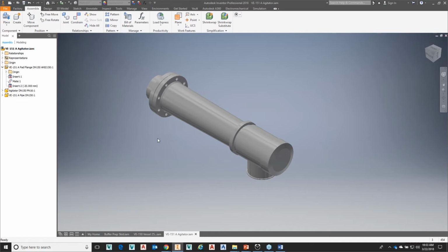So it starts early. We're going to go to this sub-assembly and we're going to create a different way to represent this, right? Now, under level of detail, this is different than just turning on and off the visibility of parts. This actually starts unloading them from memory. It makes the numbers at the bottom right go down, right? And as long as those are going down, we're unloading those from memory and hopefully using up less resources. So I'll start with this.